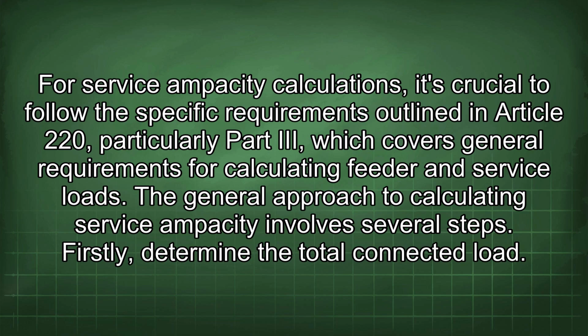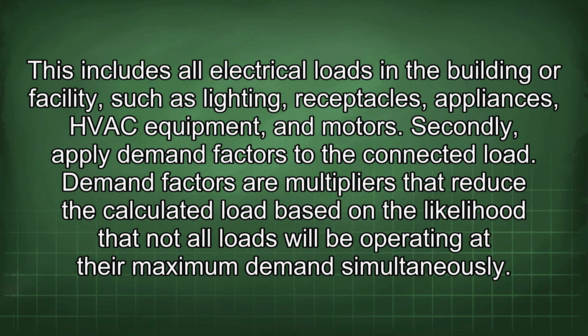The general approach to calculating service ampacity involves several steps. Firstly, determine the total connected load. This includes all electrical loads in the building or facility, such as lighting, receptacles, appliances, HVAC equipment, and motors. Secondly, apply demand factors to the connected load.